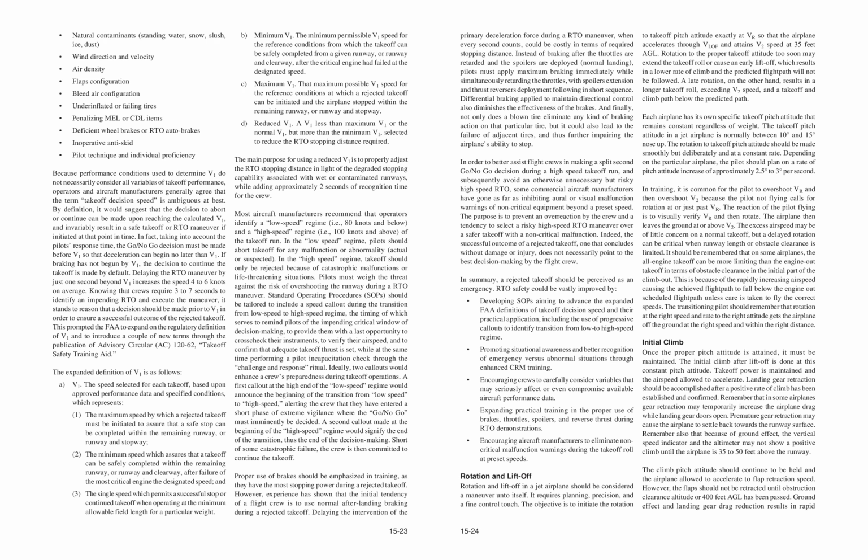Indeed, the successful outcome of a rejected takeoff, one that concludes without damage or injury, does not necessarily point to the best decision-making by the flight crew. In summary, a rejected takeoff should be perceived as an emergency. RTO safety could be vastly improved by developing SOPs aiming to advance the expanded FAA definitions of takeoff decision speed and their practical application, including the use of progressive callouts to identify transition from low to high speed regime.